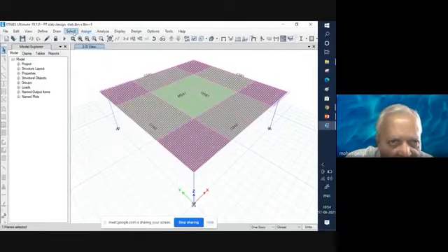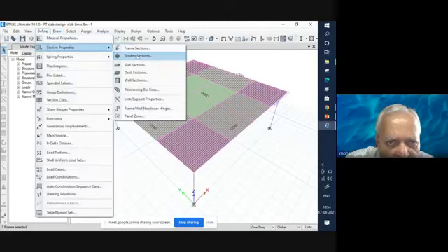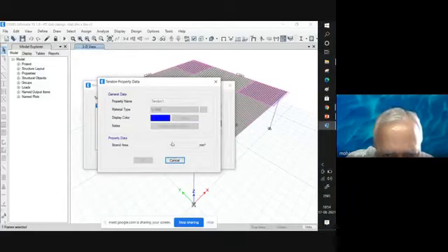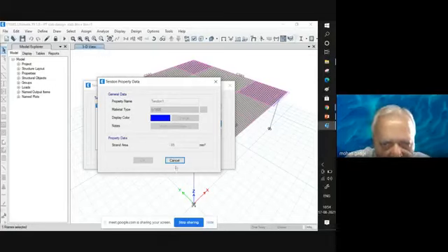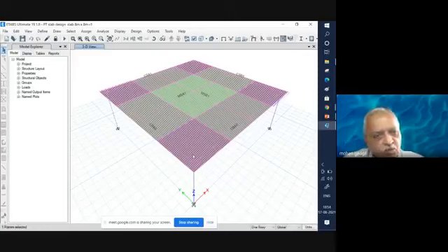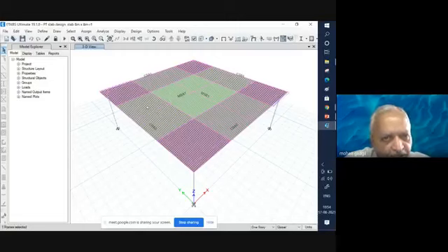As far as the strands are concerned, again on the same lines you are defining the strands. So you have a tendon section with an area, as I told you, that this 12.7 diameter tendon has an area of about 99 square millimeter. So I have taken this, and two tendons are taken in each sheathing at a spacing of 1 meter. The load we have already seen, the kind of load that we have applied, and then the analysis is done.